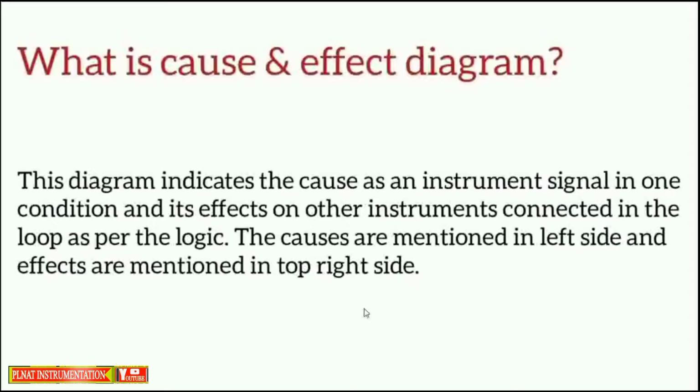What is cause and effect diagram? This diagram indicates the cause and instrument signal in one condition and its effects on other instruments connected in the loop as per the logic. The causes are mentioned on left side and effects are mentioned on top right side.